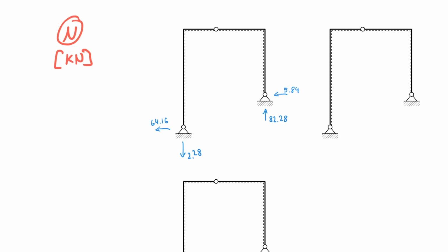And also it's constant. There's nothing else that pulls on that member. And now remember that we have the reference fiber here, and the reference fiber decides that this is the negative side and on the opposite side is the positive side. So tension is positive. That means I have to have a constant value here. And now you will see for the first time how to draw those diagrams. So you actually do that on a per local basis.